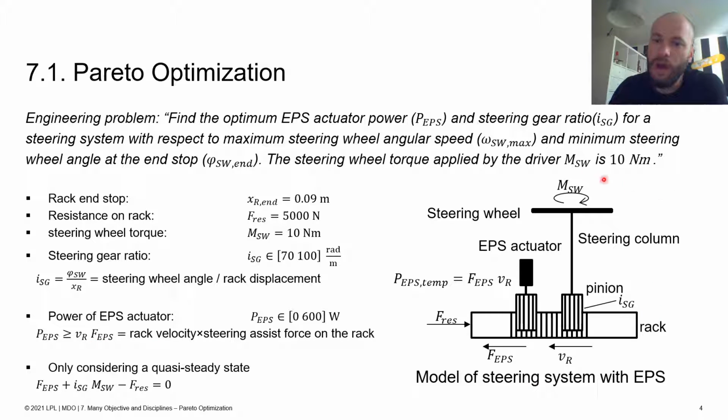For solving those equations, we assume a quasi-steady state. So here's just an equilibrium of the forces consisting of the force of the EPS actuator. Then we have the input force due to the input movement of the driver, and we have the resistance force, and this should be in the equilibrium. Once again, I want to stress that formulas like that in the exams are given, so don't be afraid. You don't need to be some expert or some automotive engineer.